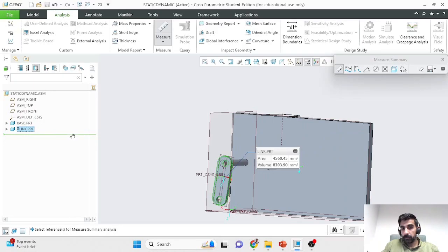And hopefully we can understand how Creo can compute this, because it knows how many surfaces there are. From that, it can calculate the total surface area, and it knows the depth and all the dimensions in 3D. And from that, it can calculate its volume. And very simply, for it to calculate the mass of this component, it needs the density. Density is the mass per unit volume. And we can either go to the settings of that part and manually enter the density, which would be in the units of kilogram per meter cube or similar units in different systems of unit.